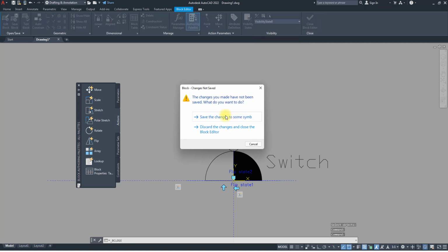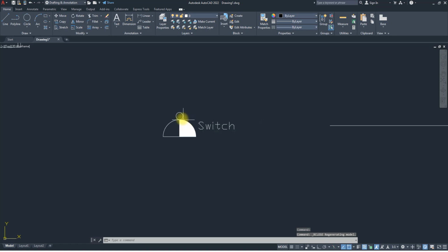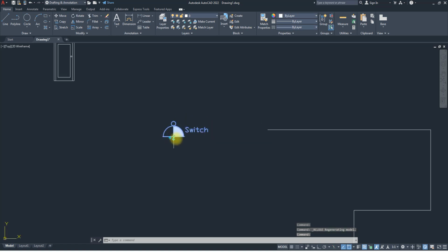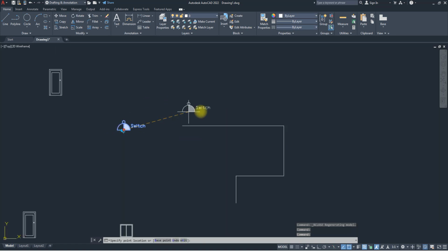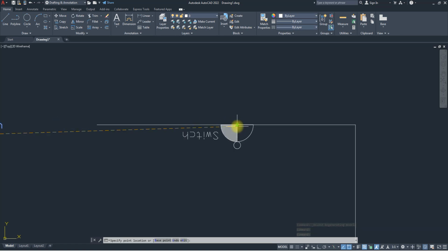So you are going to see this now. If we close this, accept changes. If I select this guy, I have the flips and I have this alignment. If I bring this guy here, I can align it. You can see, but by the time I move down, notice what happens to the text. Can you see? So which is why this flip comes in handy. So if I use this flip, the text remains the same. Am I making any sense? That's why this flip is important.